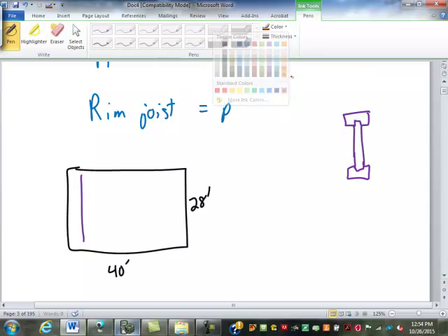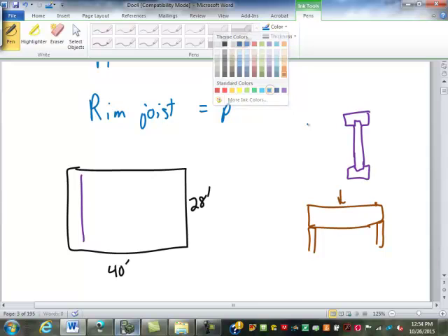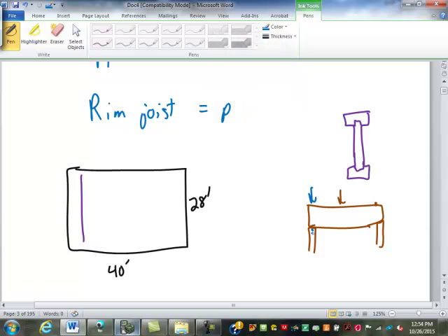They're just fine when they're spanning. They've got a lot of strength. You can put a lot of weight right here. The problem with TGIs or any I-joists is the load right here, right above the bearing where they're being held up. The center web here is not structural for compression. That center web is only structural for bending. So if you put a heavy load right here, it can actually crush that center piece, not plywood even, it's usually just a fiberboard, an OSB. It can crush that.